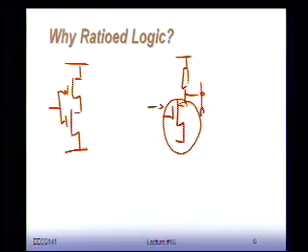But now you can see that in any of those circumstances, you're always going to have a resistive divider. VOL is not going to be 0, but some number in between. And obviously, from a noise margin perspective, I would like it to be as close as possible to ground. If you want nice noise margins, I would like VOL close to 0. So there's an interesting trade-off here. You have your load resistance, and then you have your NMOS resistance.